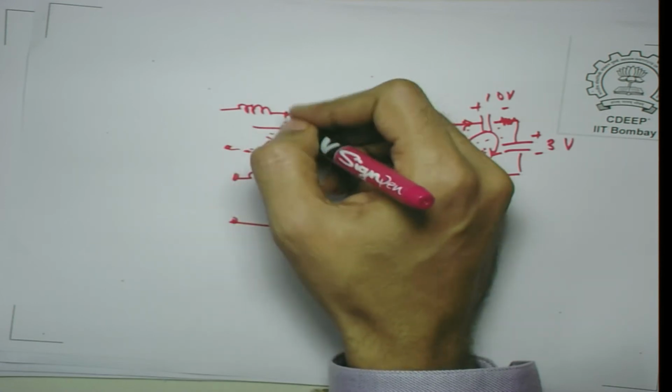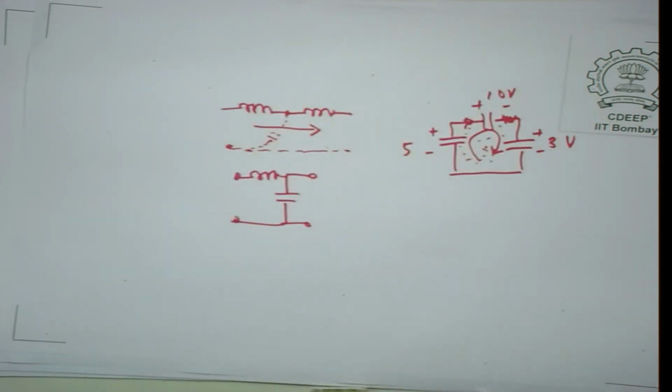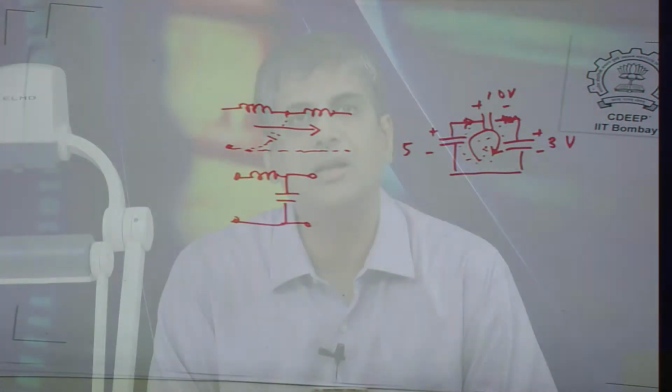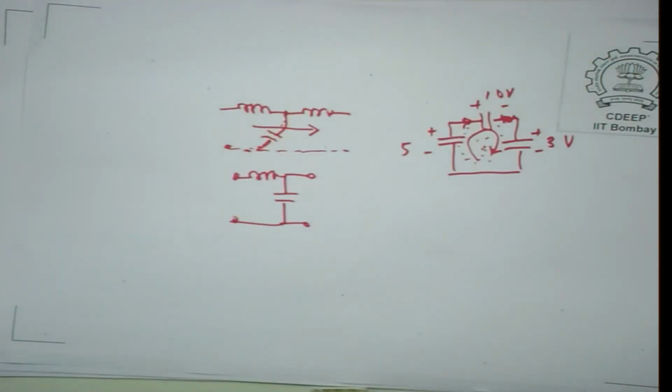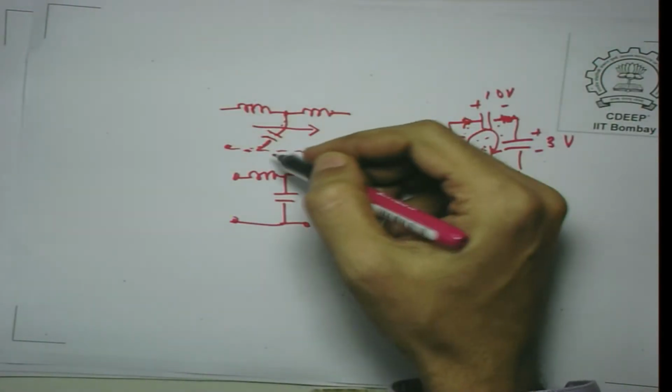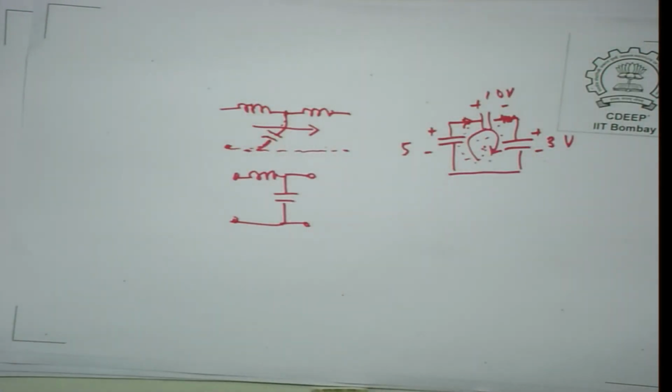So, in some sense any metal separated by a dielectric or insulating material would have a bit of stray capacitance, and that would really save us. In this case you could actually specify these currents independently. So, this needs to be looked at carefully. If you consider ideal circuits, there are some constraints on how you can specify the initial conditions. But if you take real-life situations, you normally see that some non-ideality helps you in avoiding such a situation.